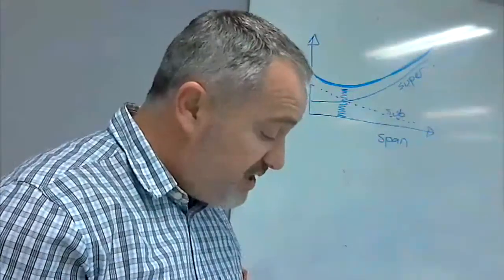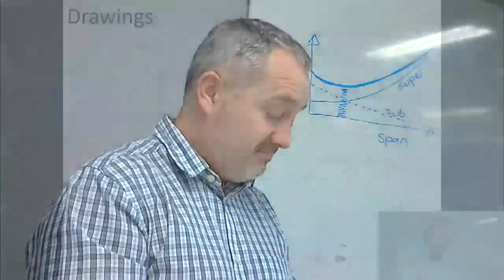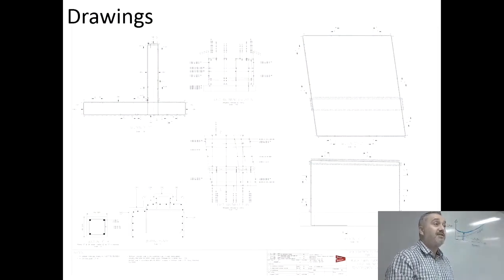How long do we design bridges for? How long do we expect them to last? Well, Eurocode 2 is for reinforced concrete, but Eurocode 0 gives 120 years, and buildings are 50, unless the client specifies otherwise.